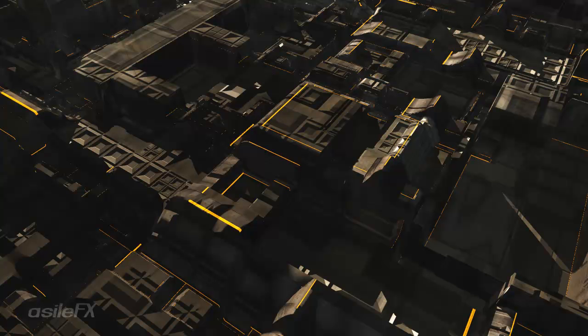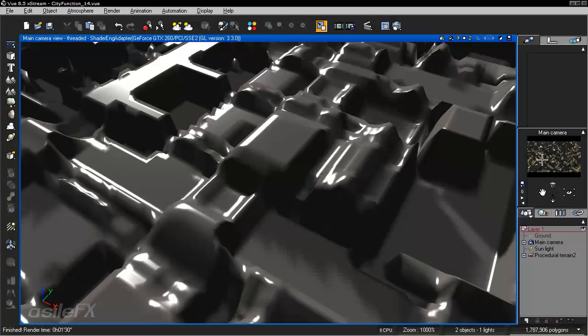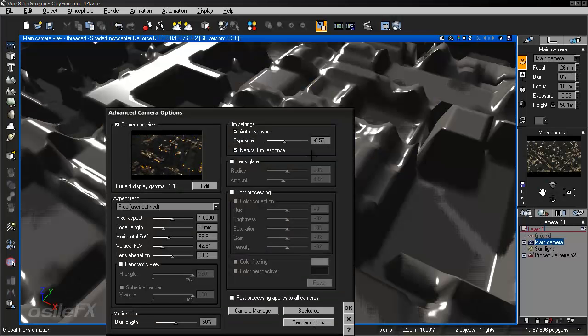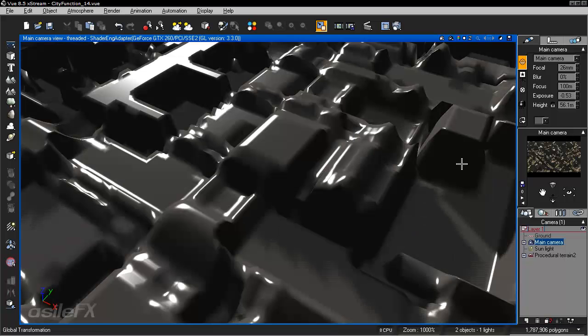that I have right now, or the highlight variability, I think is too intense, and the overall value is too high. So I'm ending up with these very bright white areas that are maybe too much. If we add a bit of glow to the white areas, you can use the lens glow or lens glare. If you double click on the camera, you can turn on lens glare. That works pretty good for it. Or in post, you can take care of that because it is, I mean, more realistic to have peaking areas like that with this type of surface.